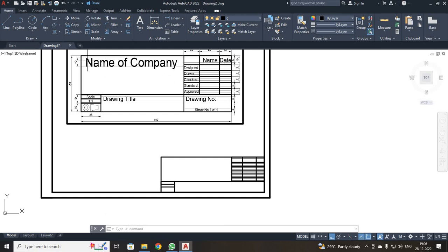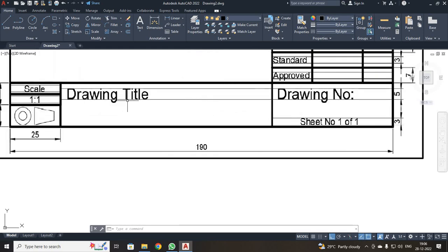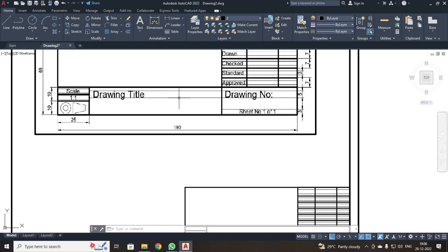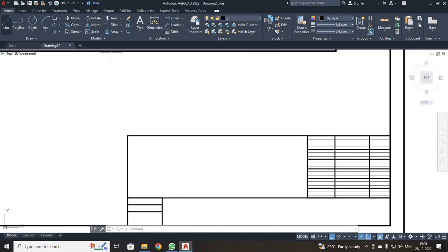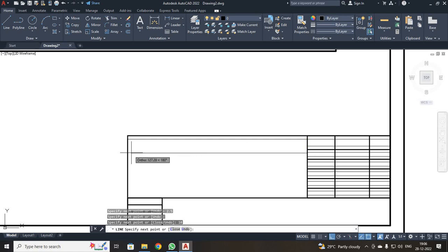See, I have a 10 mm line over here, then I have a 5 mm line over here and a 3 mm line over here. I have to complete these 2 lines. So what I am going to do is, once again, first complete your 10 mm line. I just clicked over here. From here it is 2.5, enter. I made my first click. Okay, on your y direction it is 10, and moved to your x direction and just made a click. So I have drawn your 10 line.